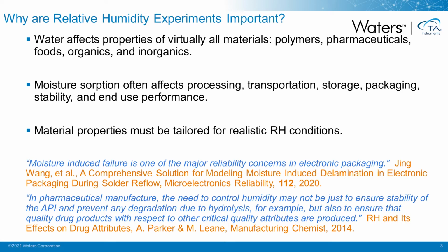It says, in pharmaceutical manufacture, the need to control humidity may not be just to ensure stability of the API and prevent any degradation due to hydrolysis, for example, but also to ensure that quality drug products with respect to other critical quality attributes are produced. So understanding the impact of humidity on materials is a very important thing.